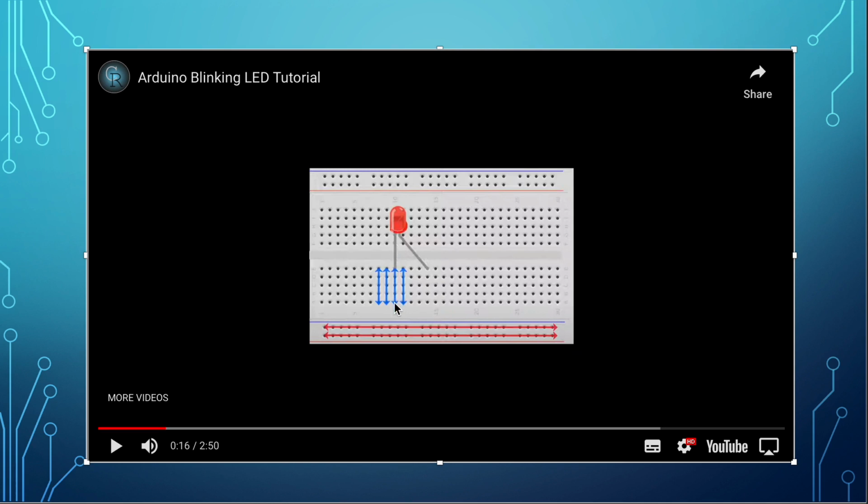If we use any hole over here, it would have a connection to this LED bulb, right? Similarly, if you have a wire from here, and you need to pass that information to something over here, it will transfer it internally because these are interconnected, right?